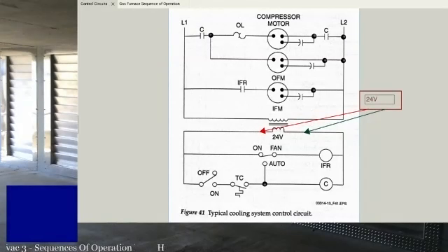If you leave the fan on, especially if you're not talking about a system that has multiple fan speeds for fan on and for fan on with cooling, you know what I mean? So continuous fan, a lot of ECM motors have a continuous fan speed that's something like 30 or 40% of standard speed, and then it ramps up when you need cooling. And then communicating systems will have a startup period where the fan runs at a lower speed to try and dehumidify before it lowers the sensible temperature.